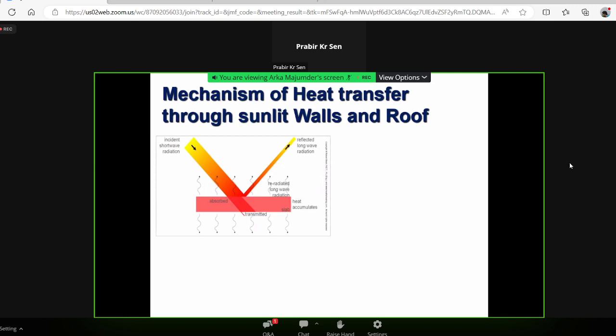Again, in the morning hours, the walls have become cool. Outside has become cold, but the outside wall is taking a little time to get heated up. So in the morning hours, though delta T is more, the heat coming inside the room will not be that big because the walls are still a little cold. Throughout the year, through the seasonal change, throughout the day, this will happen. So it's a little complicated. So what will be the heat load?